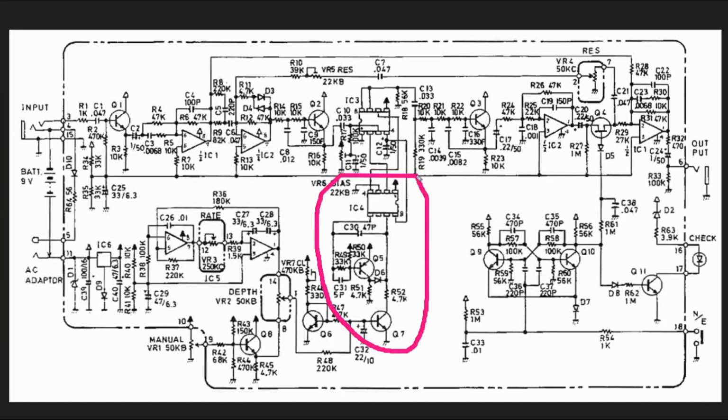Okay, so here's our clock driver chip, and if you remember, the clock driver frequency is set by connecting an oscillator between this pin and this pin of our device. And so we have a capacitor here. We have a resistor and capacitor in parallel onto the base of a transistor.